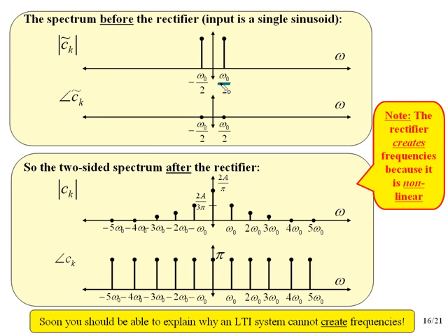The omega sub 0 came from finding the fundamental period of the rectified signal, and then finding the fundamental frequency. So that's why we divide by 2. It was a sine wave, and we just assumed it was zero phase. So we have something that looks like that.